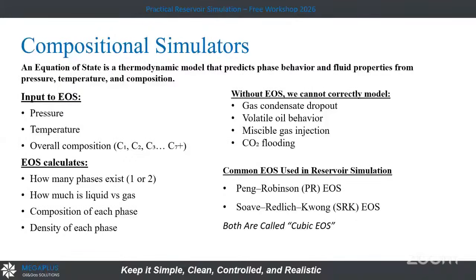The third part, as an example, is a gas condensate reservoir, not oil. Here we have a gas condensate, the CVD, constant volume depletion. We have a gas reservoir, as you see in red, and then we are going to decrease the pressure. So the first dew, or first condensation, will happen. We have the saturation pressure here, but it's not a bubble point, it's a dew point. And after that, we will open, as you will see here, okay?